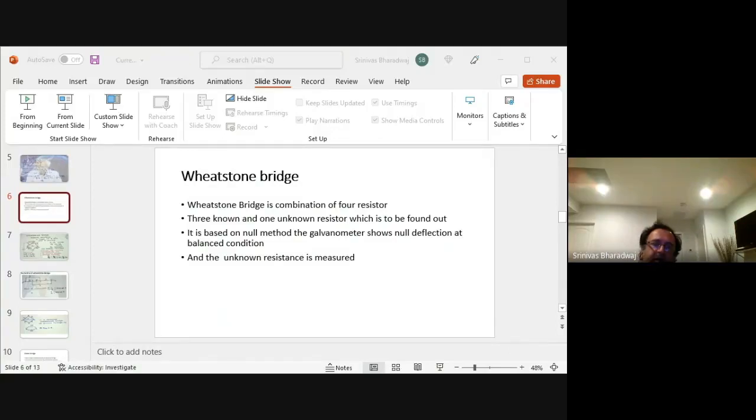So in this case, you drop the R and you can pull out the R. There's no current through, and therefore the net resistance R equivalent is 2R and 2R in parallel. 2R and 2R in parallel is what? It is 2R by 2, which is R. Okay, so equal.